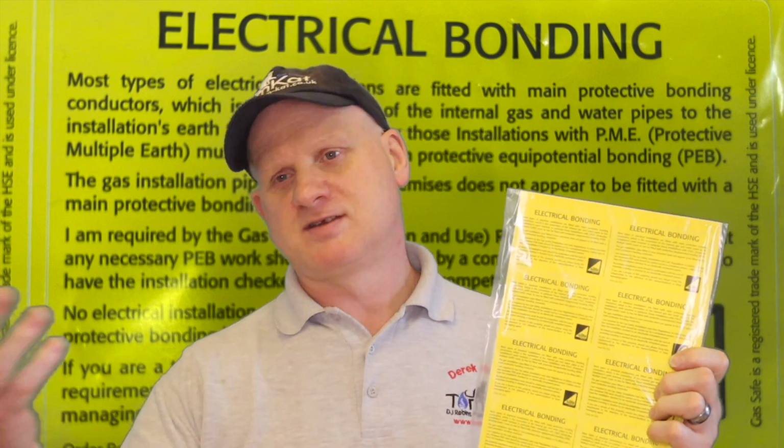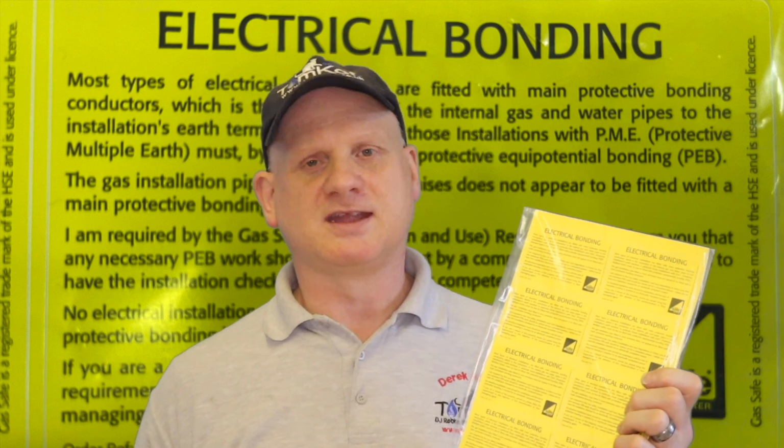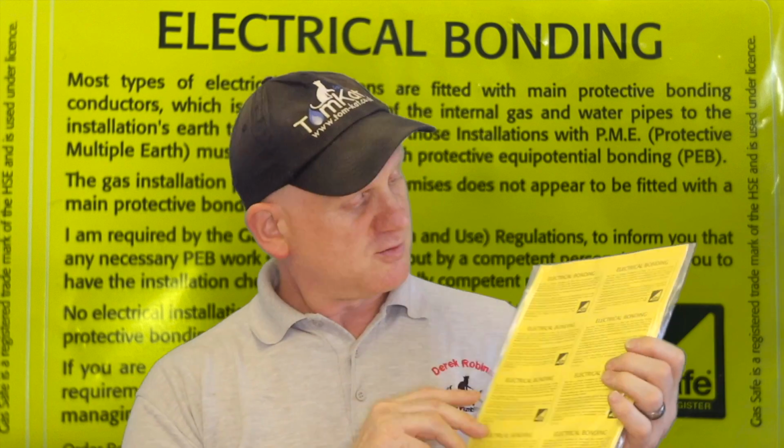But what is this notice then? So we advise, and we carry these stickers, which you can buy off the internet, which you will leave at the gas meter. So you can either stick it on the meter if you want, or you can stick it in the meter box if it's outside, as long as it can be read and easily seen by the person in charge, the owner, the tenant, the landlord, whoever. So that's what we need to use. We need to use one of these electrical bonding notices, because remember, we're not electricians, we're gas engineers.